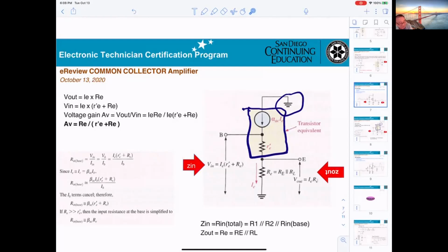That's why on your TV or your speaker, the impedance can be 10 ohm, 8 ohm, 5 ohm, or for a TV maybe 75. That means the amplifier output has to have the same impedance to get the maximum power.